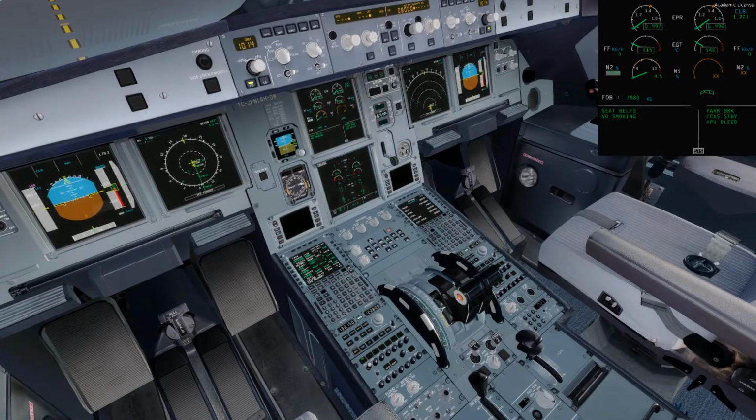Today we are using the IAE motors, which are not the motors I use the most, as I use the CFM, but we'll see how it goes as we fly from Istanbul to Ljubljana. And the engine number 1 is starting. As we can see, the EGT is rising, and also the N1 at least. And the fuel flow is about 400 kilograms per hour. And when the engine is stabilized, we'll turn on the engine number 2, and then we'll call for the taxi.